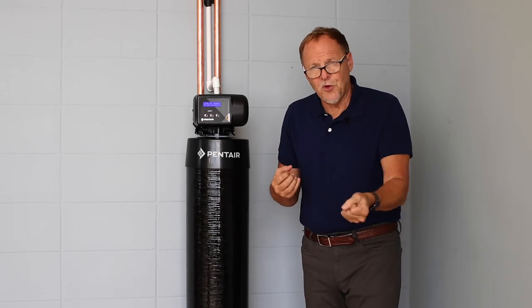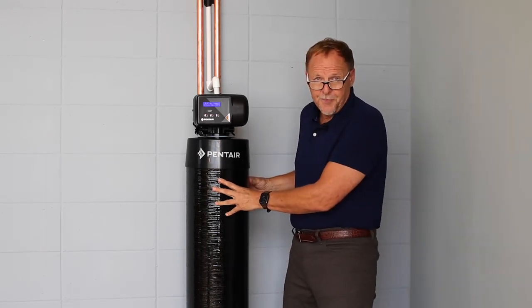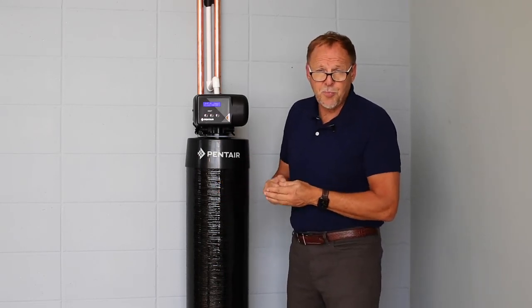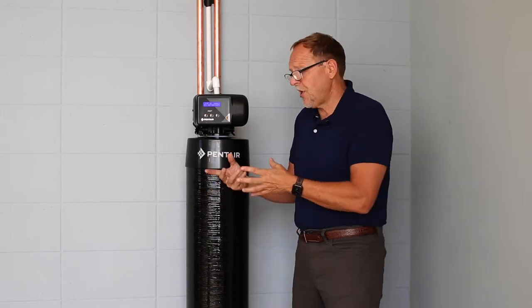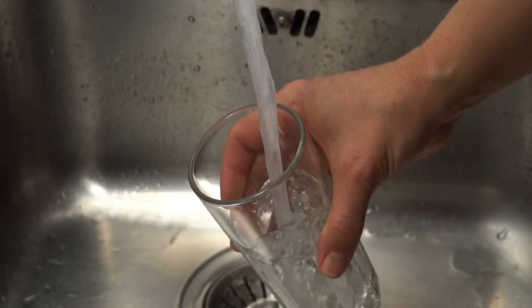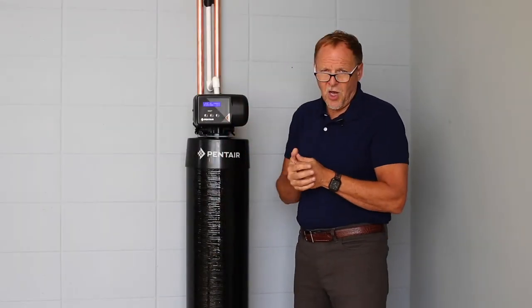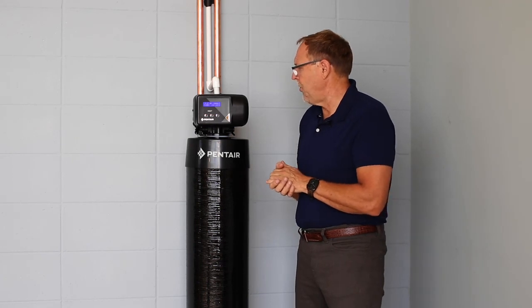Just like an iron filter puts air in the water, carbon is very porous as well. So when a carbon filter is brand new, it's also going to push off air for at least a few weeks. I go upstairs, turn a faucet on, show the customer the cloudy water, set their expectations, and I'll have less problems down the future. And that completes it for your carbon and neutralizer startups.